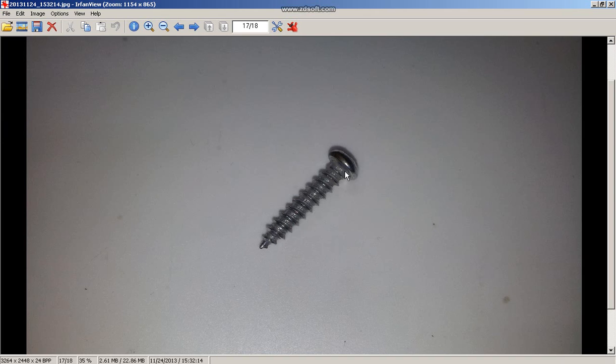So the total length of the thread area is 19, and if you look through this image, the thread area has constant diameter until about 14 millimeter. We have 1, 2, 3, 4, 5, 6, 7, 8 revolutions until 14 millimeter, and for the additional 5 millimeter we have decreasing diameter until 0. In the additional 5 we have 1, 2, 3, 4 revolutions, so the diameter is 0. Okay, I will show you how we do this in SolidWorks.